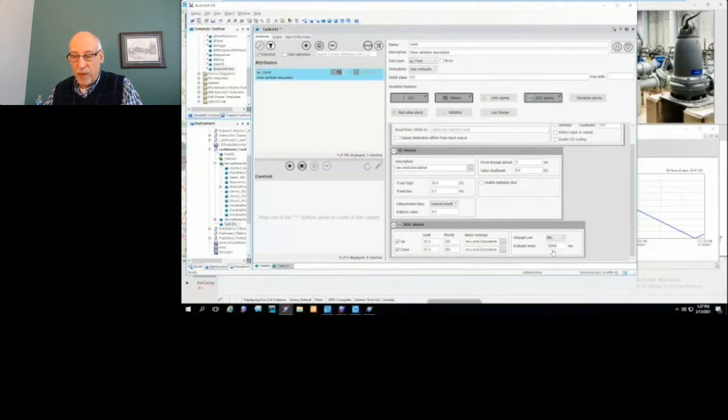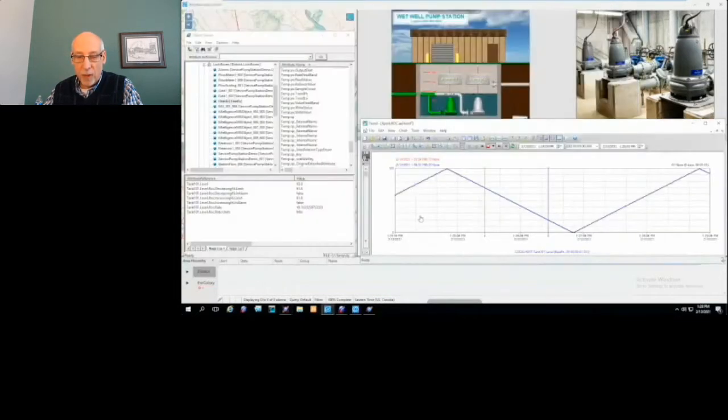So every 10 seconds I'm going to read the value, and then when I read it again, it's going to do the math to determine what the slope of the line is, and then generate an alarm if that line slope has changed within an alarm range. So I'm in my object viewer here, and you can see that's the current level, and that's the different alarm limits, and there's the actual calculation that's being generated here, that minus 40 in this case. But right now it's 61.